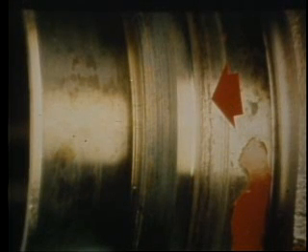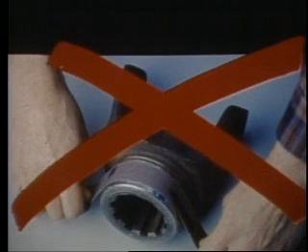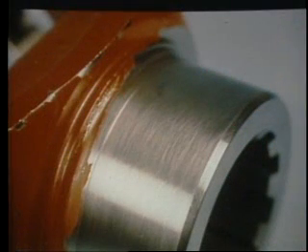If the seal surface of the yoke has any more wear than what could be considered polishing, the yoke should not be reused. A yoke that is worn cannot successfully be repaired by using emery paper or crocus cloth to clean up the surface. It is unlikely the seal surface can be made smooth enough by hand to meet the industry standard of 10 to 20 RMS.